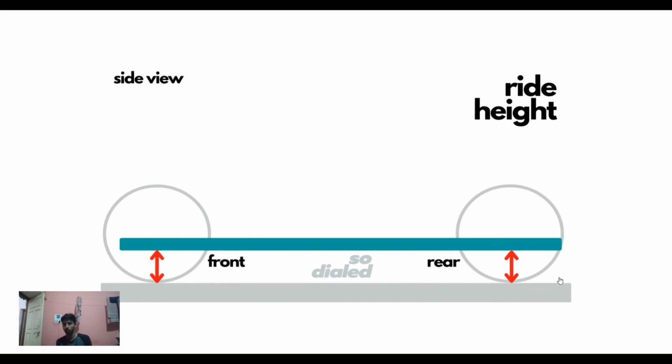So if you're choosing a lower chassis height, be sure that the track you go on has very short bumps. Not too high of a bump, so that you can manage the suspension. If the bumps are too high, then your wheels will probably hit your chassis, or it might not effectively use the suspension travel. It becomes uncomfortable. Lowering the chassis height will effectively lower the CG also, and it will also bring all the other pros which I mentioned previously, like the stability, the comfort, and increased handling capabilities.